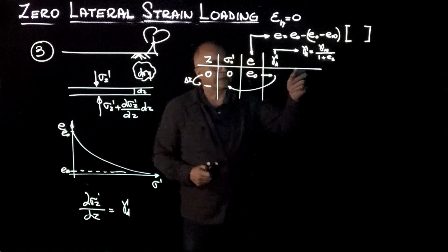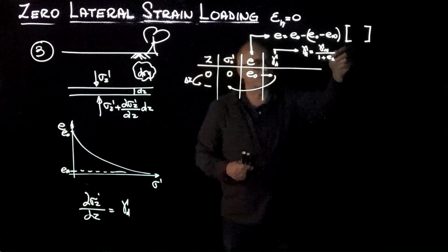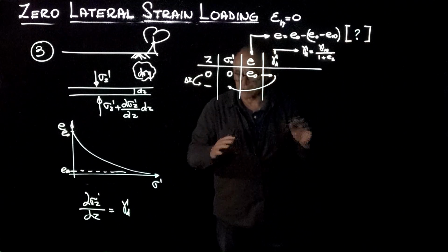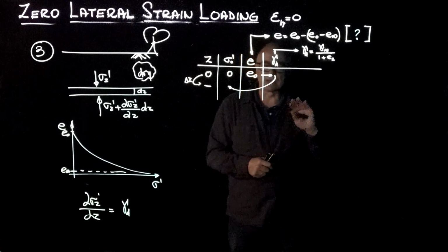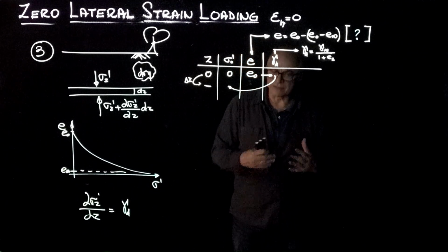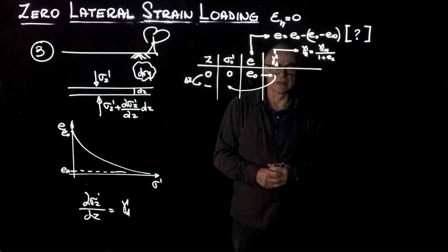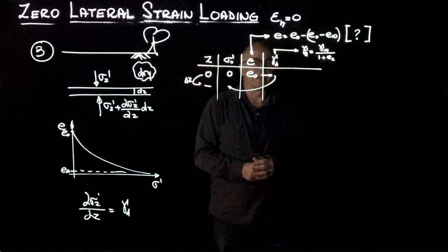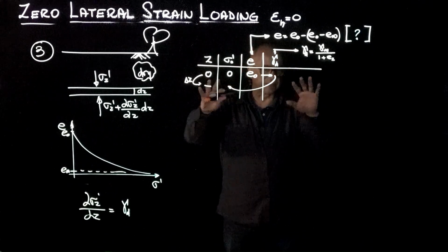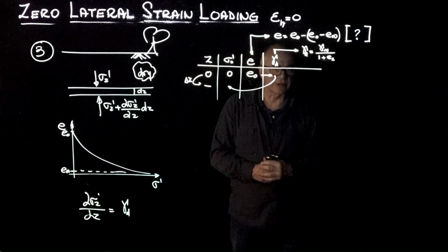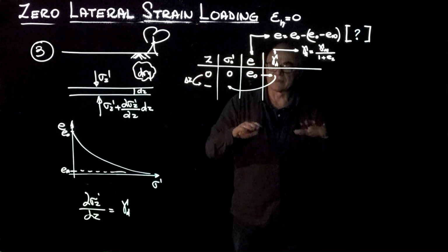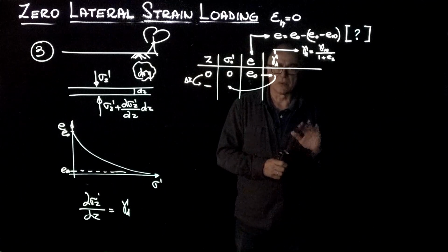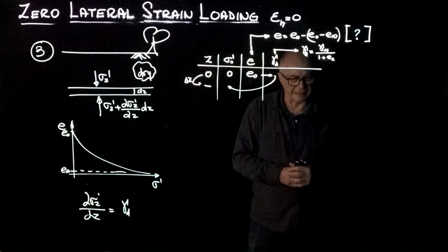The other parameters we are going to see how to determine. But there are different functions. They have this form with different components. Here could be the exponential, power, hyperbolic. We are going to include a series of very robust, very reliable functions at the end of this presentation. Please take a look. Using those functions and those asymptotic void ratios, we were able to predict the evolution of effective stress and void ratio with depth under a wide range of situations. We are going to include those as well at the end of this video.